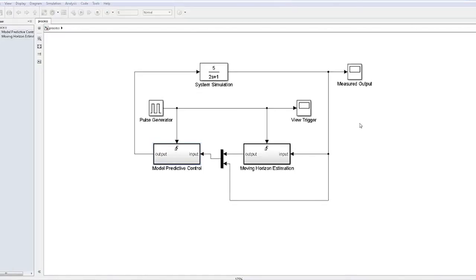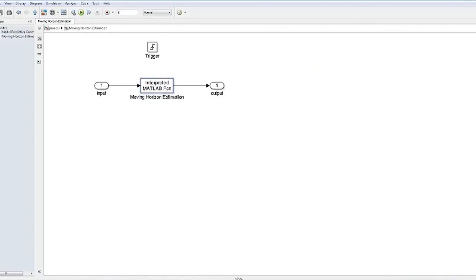So, on a first principles model, you can do any of this for any type of model, right? Yeah, you can do it for any. Just for simplicity, I just showed a linear model here. But this could be a very nonlinear collection of differential and algebraic equations. And this simulation block here, you could also replace with an S function if you want to use the Matlab integrators, or you could put another APM block in here and use that, saying I have these inputs coming in and these outputs coming out, and use a dynamic model there, similar to how we did this function here.